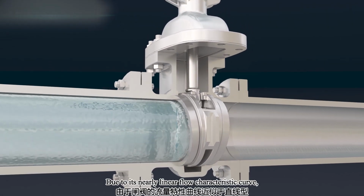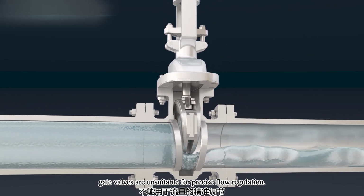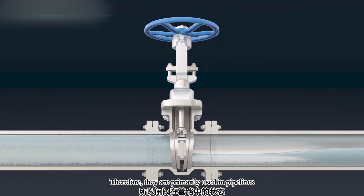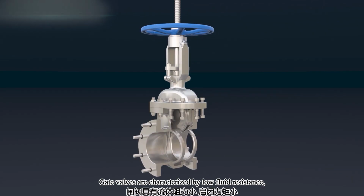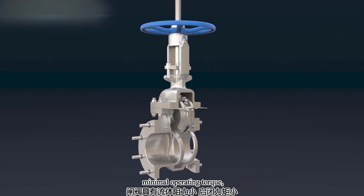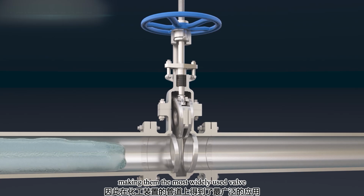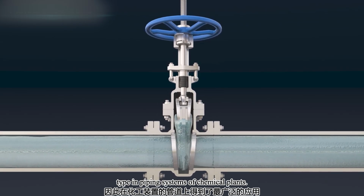path. Due to its nearly linear flow characteristic curve, gate valves are unsuitable for precise flow regulation. Therefore, they are primarily used in pipelines, in either a fully open or fully closed state. Gate valves are characterized by low fluid resistance, minimal operating torque, bidirectional flow capability, and excellent sealing performance, making them the most widely used valve type in piping systems of chemical plants.